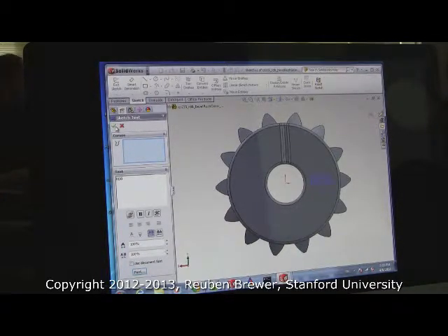What was your point dimensions again? It was units? 0.075. Oh, inches? Yeah. And then once you've got your letters looking somewhat like mine, albeit with your own initials, okay, and now press the green check mark.